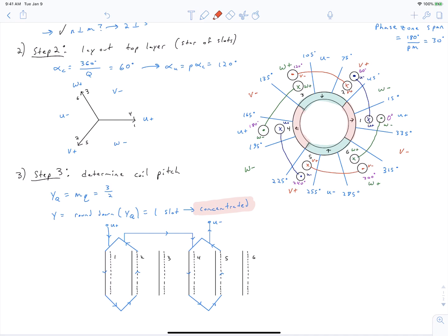but we want to come up with a formal design procedure with a formal set of steps that will always produce a symmetric winding with good winding factor, regardless of how many slots and how confusing it is to look at. And what we're going to do is go back to thinking about this in terms of our A phase zone diagram. And so the question at the moment is how should we design this 6-slot 4-pole motor as a single layer winding?